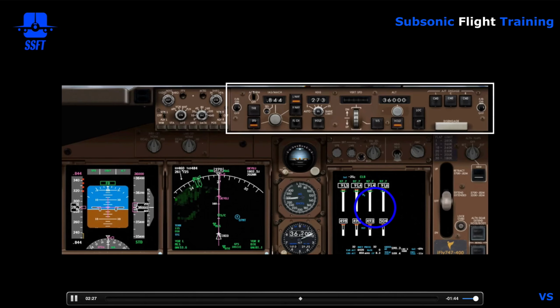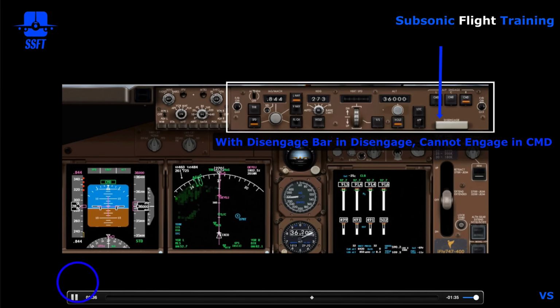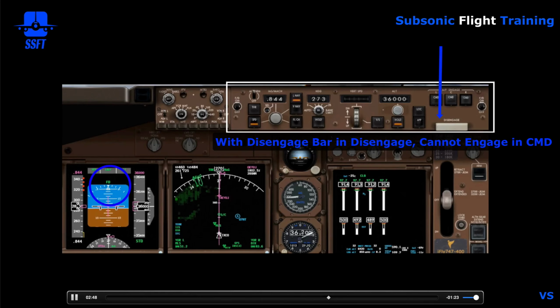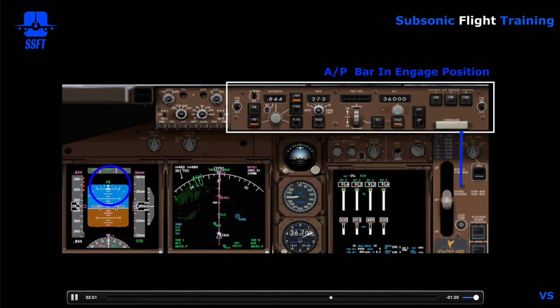So you have to disconnect an autopilot, like the center autopilot, disconnect, and then connect the right autopilot. You have to disconnect and then reconnect. There, we're disconnecting again. We're manually flying now in Flight Director. And then, of course, we can then reconnect another autopilot.